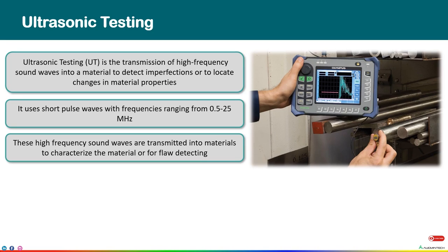These high frequency sound waves are transmitted into the material to characterize it or for flaw detecting. A considerable amount of information about the part being inspected can be collected, such as the presence of discontinuities, part or coating thicknesses, and acoustical properties.